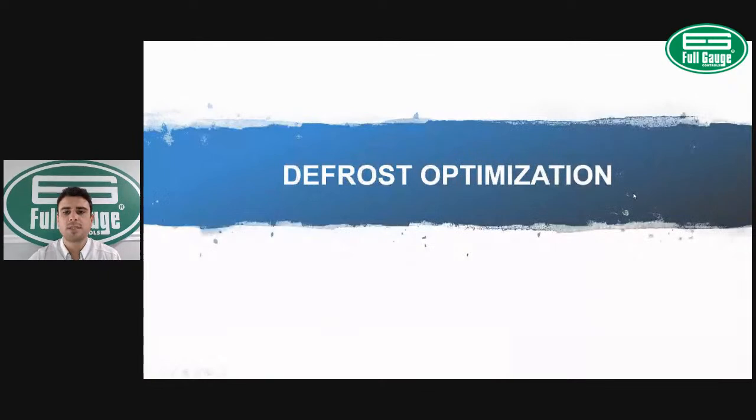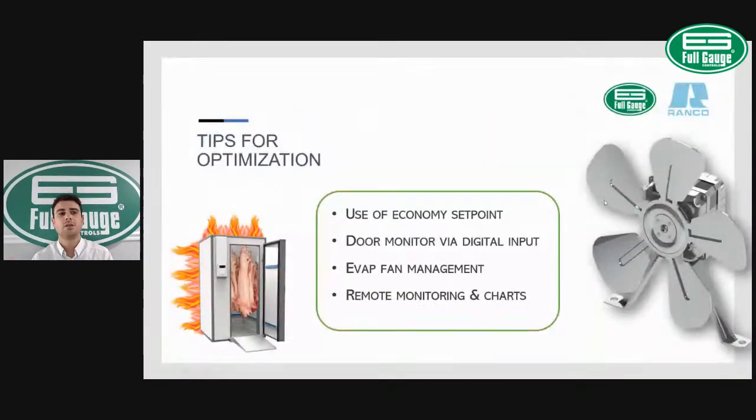So, defrost optimization. We have a few ways. Here are some tips on how to optimize the defrost cycle. One very easy way to reduce defrost cycles is the adoption of economy set point. Economy set point will actually allow reduced running of the compressor.